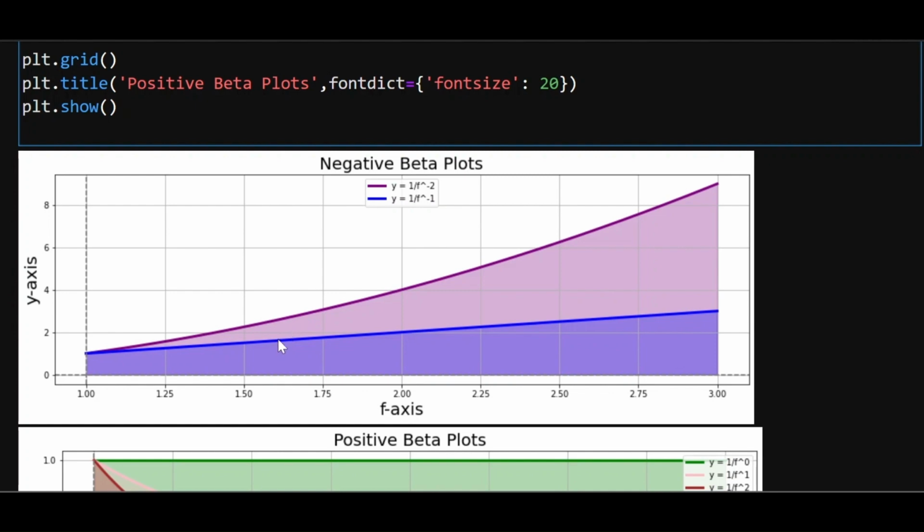Blue noise, as I mentioned, has a slope of 3 dB per decade. Because of the squaring action, this has a slope of 6 dB per decade. What it essentially means is that in comparison to blue noise, violet or purple noise has even higher power at higher frequencies, and lower power at the lower end of the spectrum.